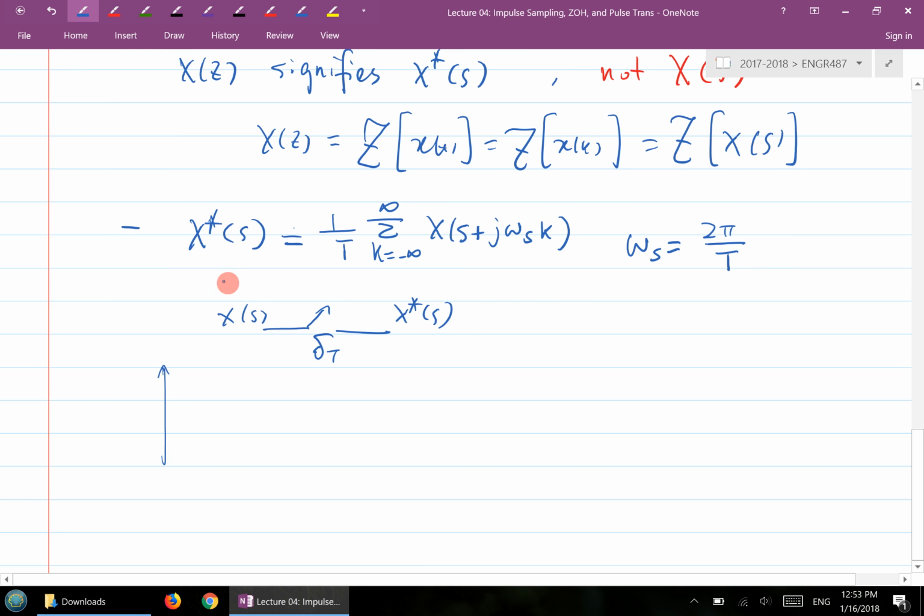if you substitute s with j omega, let's turn it into a typical frequency analysis. In control systems, whenever you have a Laplace transform and you substitute s with j omega, you're doing frequency response. For frequency response, there are two pieces of information: the amplitude plot, and also the phase plot. So you can always plot the amplitude of this signal or this system. Here's x of s, so you could plot this amplitude, which is part of the Bode plot.